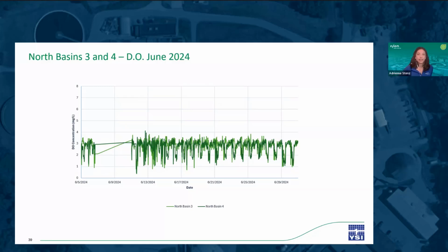These peaks that we're looking at for DO are broader and more capped, indicating that DO levels are rising and stabilizing at a relatively higher level for some time before gradually decreasing, suggesting a steady and sustained aeration response, typical of what you see in ammonia-based aeration control systems.